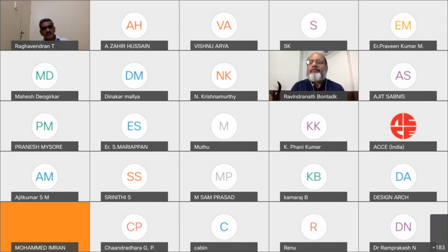And most of the PEBs we observe are of A shape, A structure, A roofing. For example, when we requested a north-light structure, most of the PEB manufacturers opted out of the contract. They didn't want to quote for it also. We asked for a 56-meter span north-light lattice structure. We couldn't get any PEB manufacturer to handle the project. So we had to go in for HR sections and a regular fabrication system.